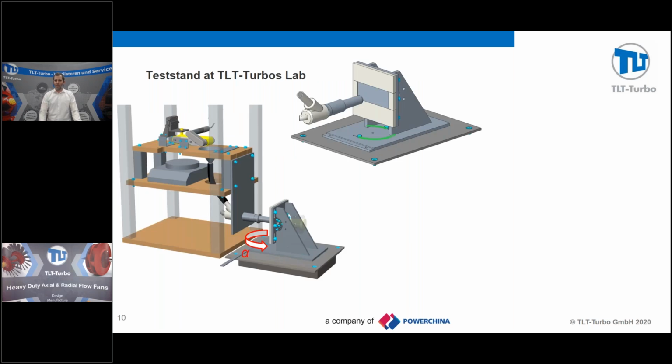To evaluate all of those influencing factors, we have a test stand at TLT-Turbo, which is depicted here in a CAD model. You can see on the left picture, there's a feeding path where we can feed in some abrasive media, which is going into a nozzle, and the nozzle is operated by pressurized air. So we get a pressurized air and abrasive media stream coming out of this nozzle. We have a holder here, which is turnable, which holds a plate of the base material or coating or whatever we want to observe. And the nozzle is shooting the particles on this